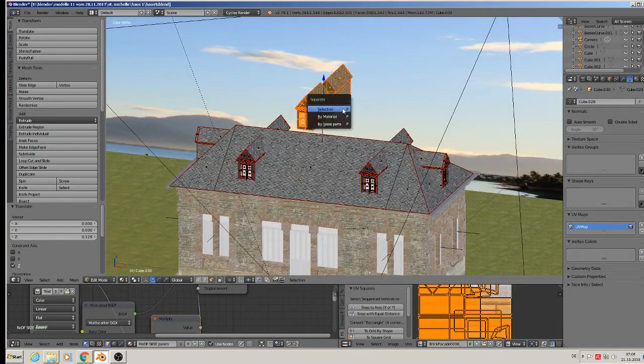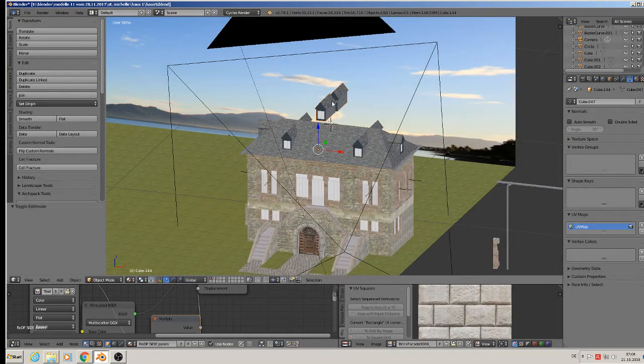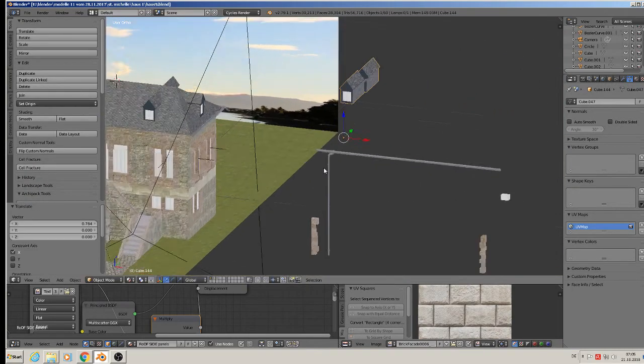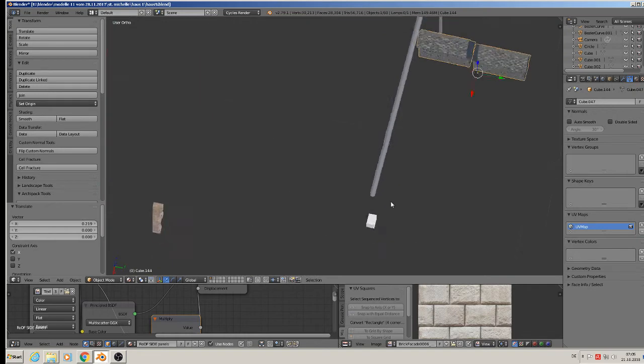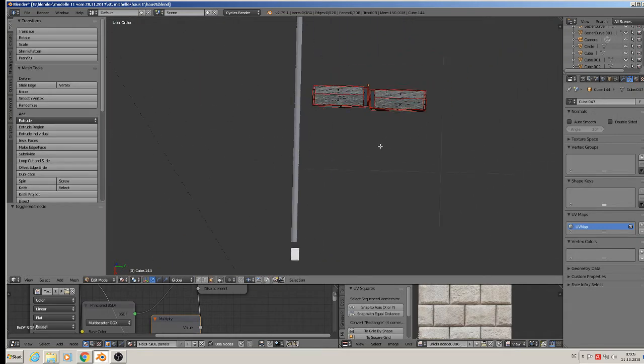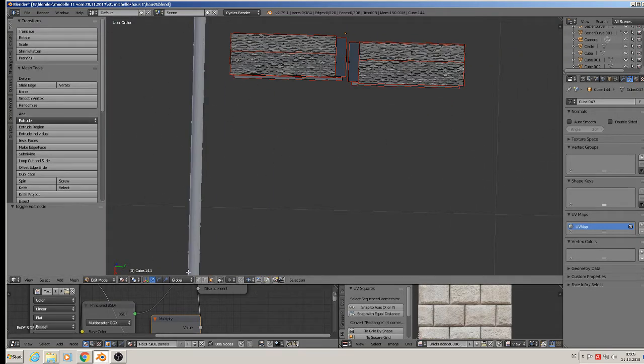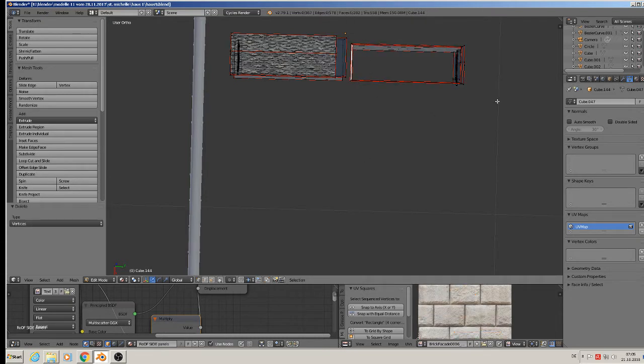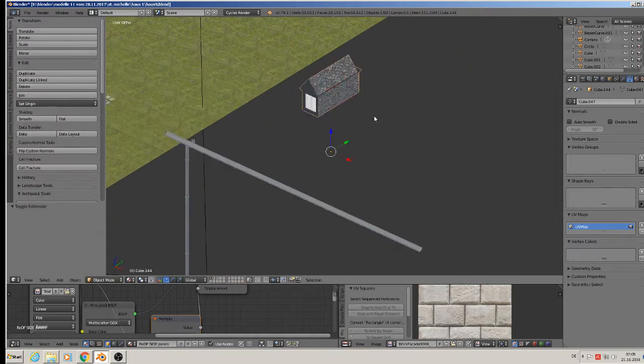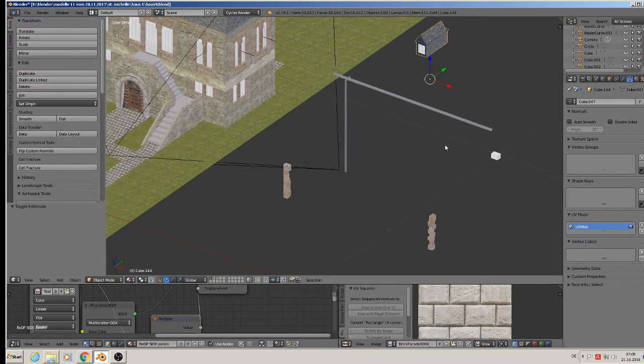So we can press P, separate the selection, and then we have that singular, and delete one of them because we only need one, not two. So with background selection, wire selection, and B border selection, we can delete that. Good. So that is all that we need.